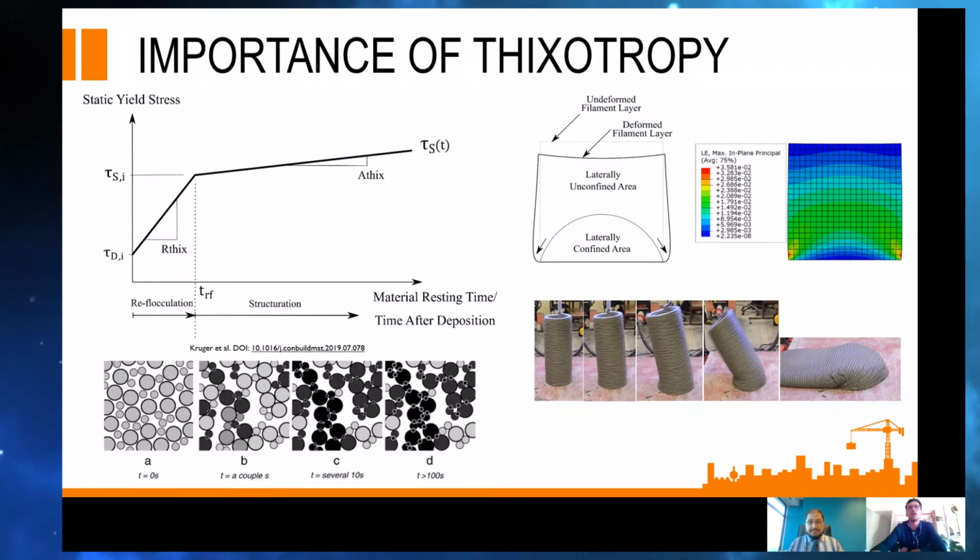Absolutely. Essentially the loading that you induce is the own weight of the filament. You can calculate this by the density of your material times g times h, rho g h. And then essentially that load corresponds to a certain shear stress. So this is sort of a rheomechanical consideration. The rheometry, the rheology of your material, fresh state property, and then the mechanical aspect of load bearing capacity. And if your material has structurated past a certain stiffness and you are inducing loading that is less, you can obviously deposit the next filament.